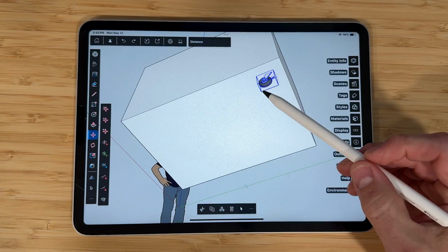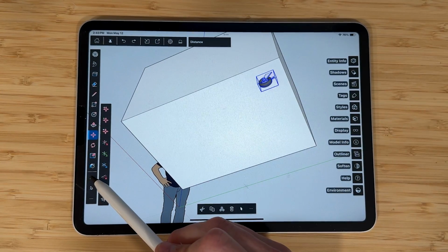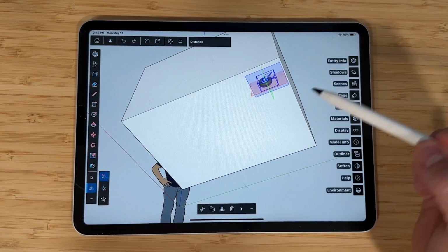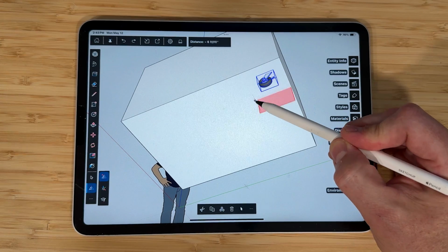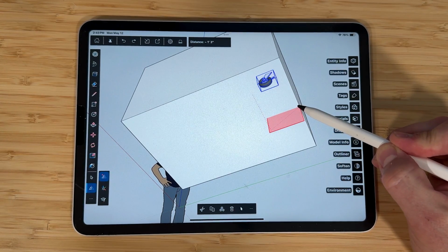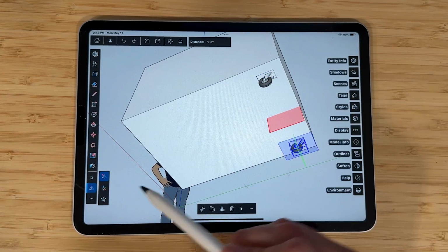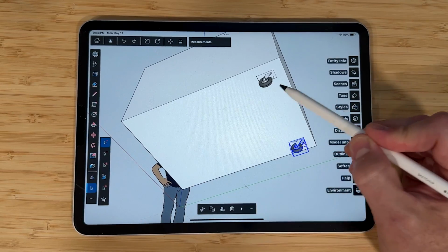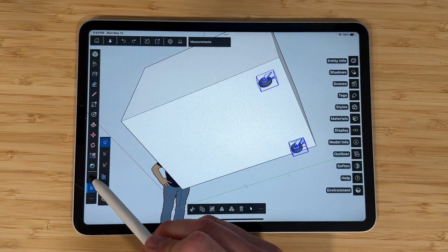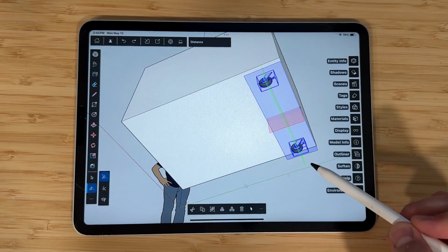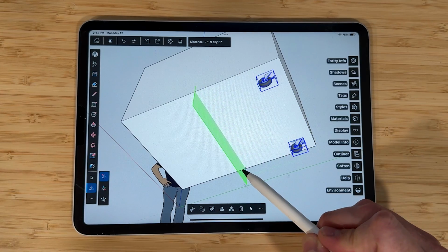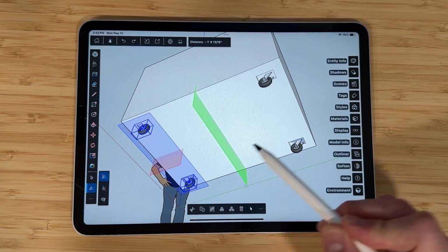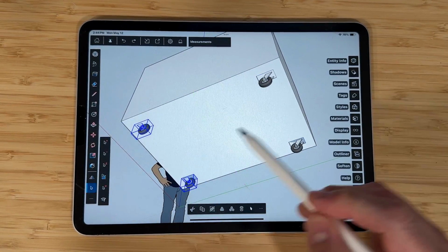And now since I have one, I could utilize that flip tool again. Flip, we're going to make a copy. Grab this surface, snap to the middle. Now it's over on that side. I want to add, grab that. Now we're going to flip again, make a copy. We're going to grab this axis, snap it to the middle. Now we got our 4 wheels on the bottom.